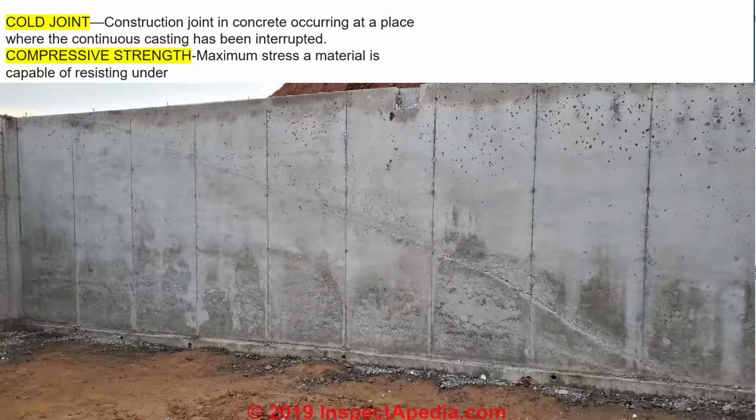There are a lot of excuses why you get a cold joint, but a cold joint is pretty much where concrete has set after being poured. You've got an open joint there. You've got voids, places where water can get into it and ruin the concrete. It's a structural issue. So unless the engineer tells you you can put a cold joint there, they're pretty much not allowed. And if it is an engineer-approved cold joint, then now it's a construction joint.